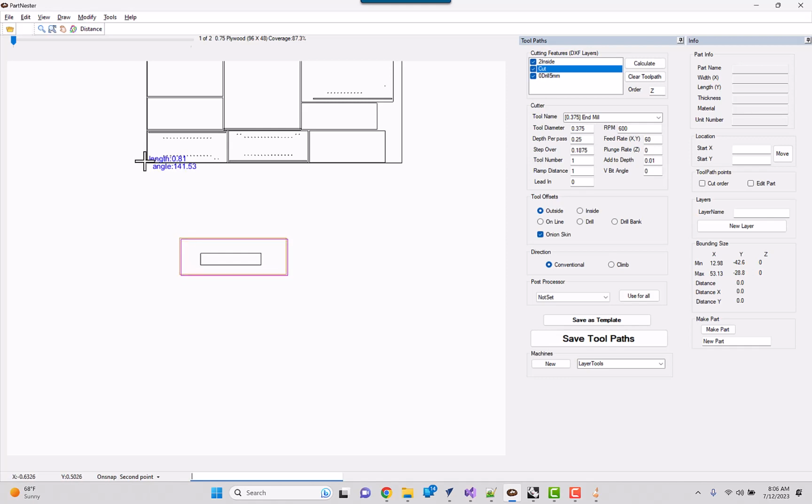I want to move it down into the Z by 3/4 of an inch. So the new value that I'm going to put in is going to be 0, 0, minus 0.75, then hit enter. We have just now moved this part down into the drawing by a -0.75, which is the thickness of the material.